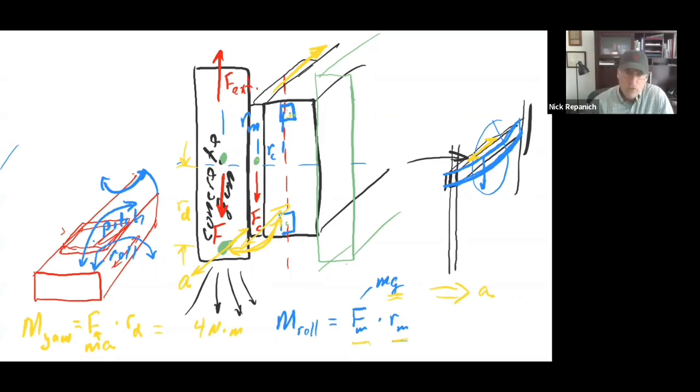Then what you do is you go to the mechanism that you've chosen. Say I chose this guy, or a larger version of this, and you would go look up the yaw moment of this device, of this actual model number. It's one of the places where you need to get away from distributors and get to manufacturers, so that you can look up the yaw moment.